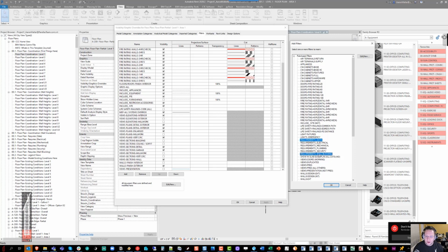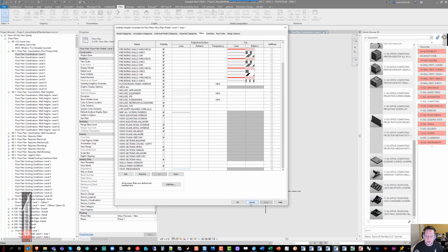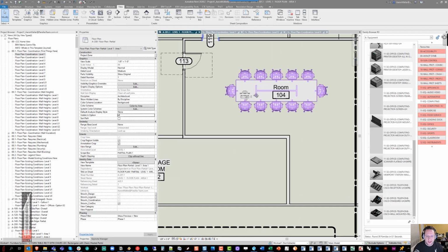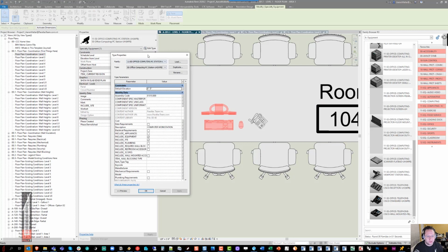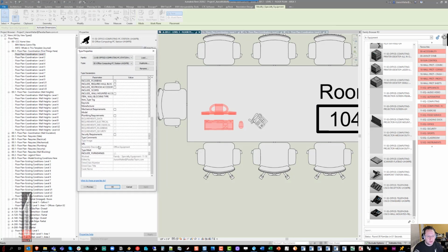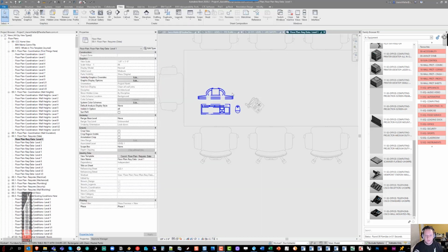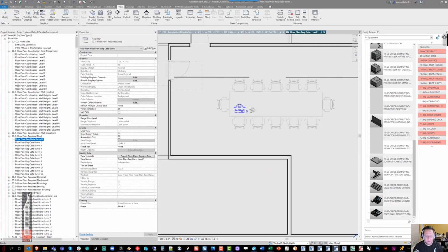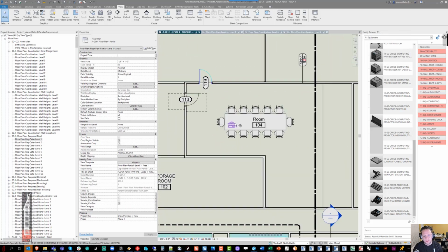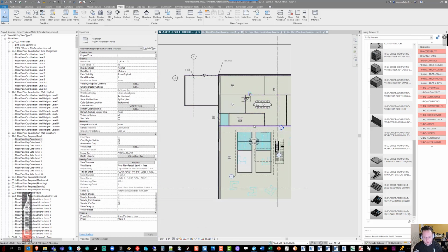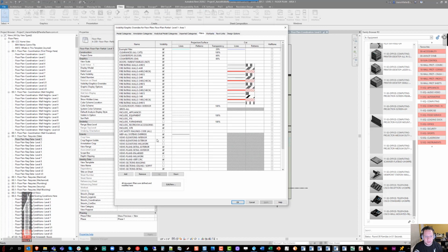There are a number of what we call requirements filters, and these are simple checkboxes that again will exist in every object as it gets loaded into the template. So if we look at the generic computer that we loaded in earlier, you'll see that similar to the includes, it also now has requirements parameters. The purposes of those parameters, of course, are simply to make the items turn color in what we call the requirements plan. This is simply done to provide a heightened level of coordination between us and our consultants, as the consultants can set their model up to automatically see that view in color.